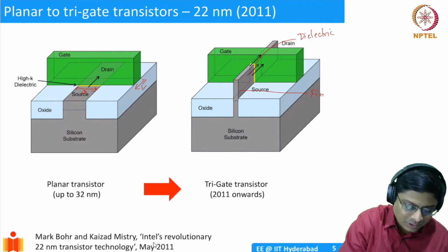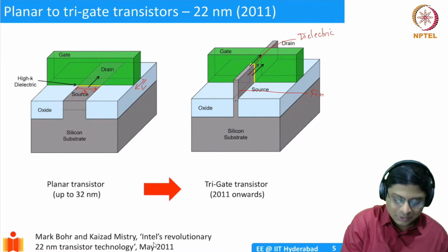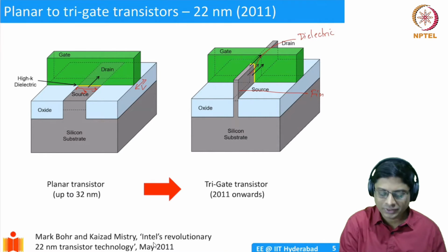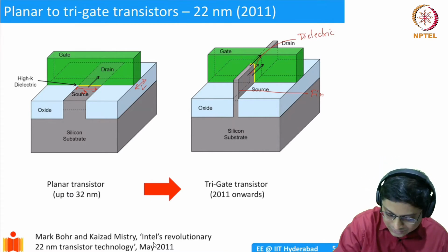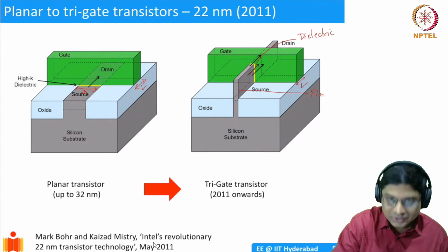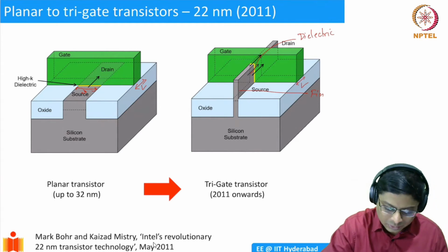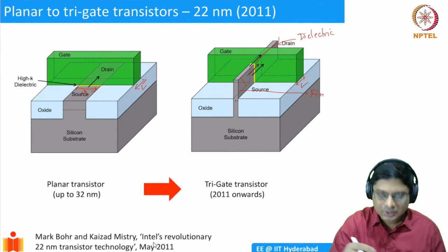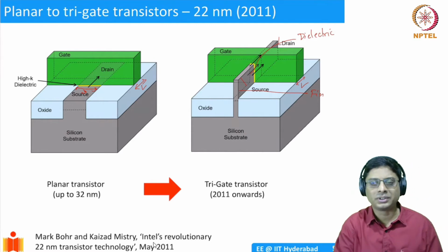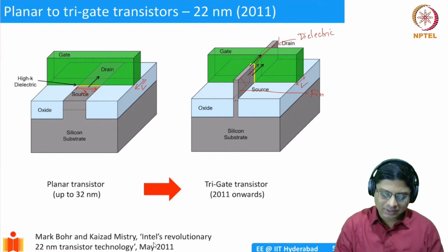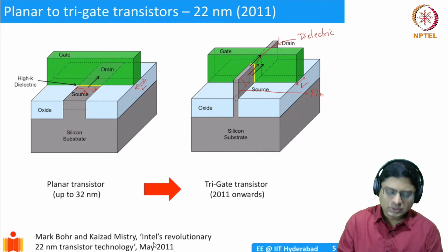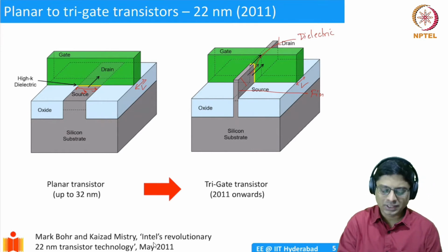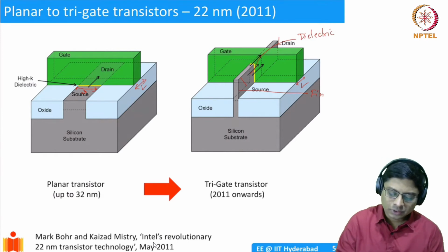So what will be the width of this device? If you relate it to the traditional width of a transistor, what will it be? We can clearly see that this is the length, because it's the distance between the source and the drain. The silicon source is here, silicon drain is here. Of course, it is doped, right? It's not going to be the same silicon. And under the channel, there is no doping. That's all there. So now, it's opposite doping, p-type doping, and then n plus source and drains. So this is the length.